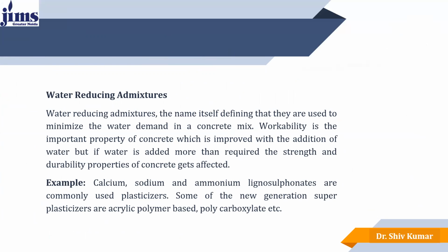Now, the first, water reducing admixtures. The name itself defines that they are used to minimize the water demand of the concrete mix. Workability is an important property of concrete, which is improved with the addition of water. But if water is added more than required, the strength and durability of the concrete may get affected, because excess water may cause the problem of bleeding, in which the major part of the cement gets removed with the water.